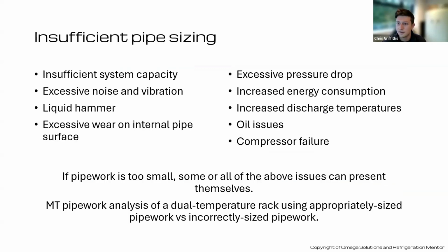I love it. So let's jump on to the first one, which is what happens if we have pipes which are too small. I think that's probably what most people are going to find rather than the other side. If you want to cut costs when you're installing, you're probably going to look, oh, can we get away with a 3/4 inch pipe there instead of a 7/8, or 1 1/8 instead of 1 3/8? So as we go through, there's quite a few issues that can occur from insufficiently sized pipes.